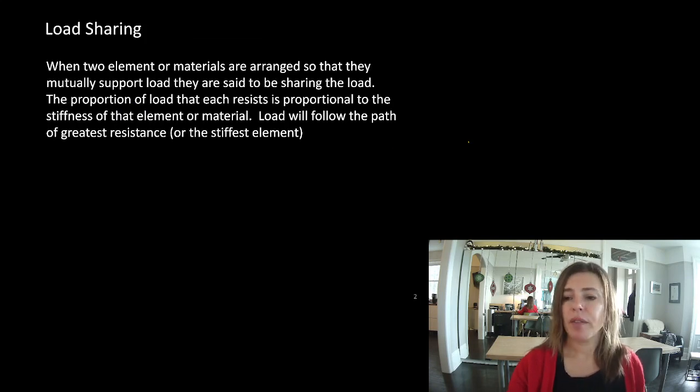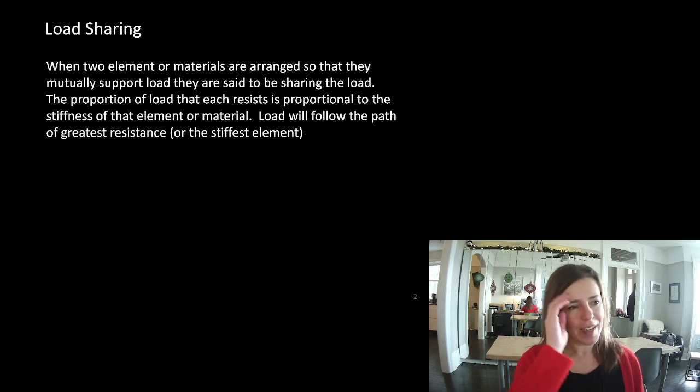So load sharing. Load sharing is when two elements or materials are arranged so that they mutually support the load, they are said to be sharing the load. I'm missing a comma in there, I believe. The proportion of load that each resists is proportional to the stiffness of that element or material. Load will follow the path of greatest resistance.